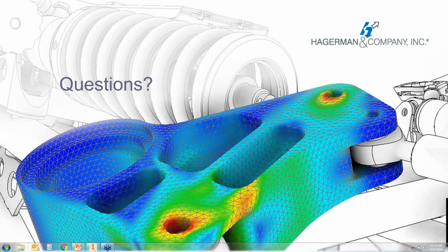It is. There's a couple of gotchas you have to watch out for when you're getting into a dynamic loading situation. The dynamic simulation engine or the kinetic engine can help you define those loading points in time, and you can watch that snapshot in time. And John, to answer your question, yes, that is Inventor Pro.